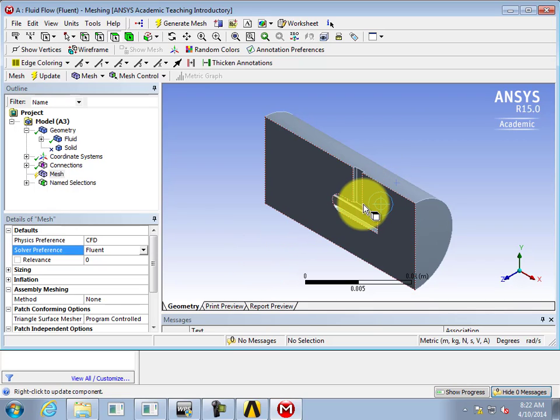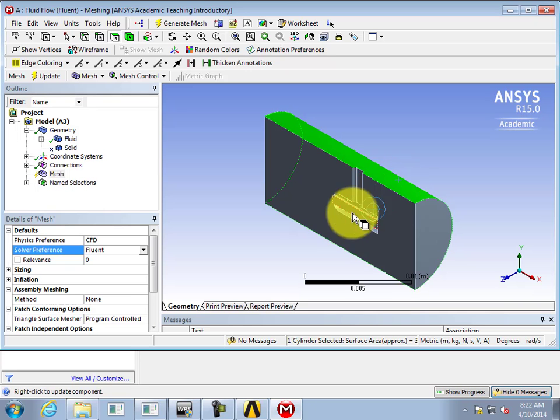All right, so what we're looking at here is potentially a probe that would be coming down from an aircraft and measuring the velocity that the aircraft is traveling at. For an external flow analysis, you have to put the object in the flow and then make sure that the domain where you're going to mesh is far enough away, that's why this is called far field, far enough away that any of the effects of this object being in the flow are not felt by the wall. Because if the wall's too close, it's going to change what this thing would actually experience out in atmosphere where there are no walls. So you have to make the wall far enough away that it doesn't have an effect on the flow around the object within the flow. That's a lot of flow.